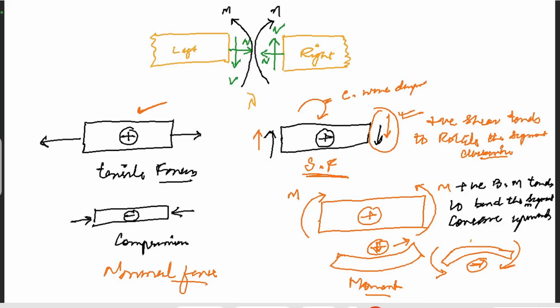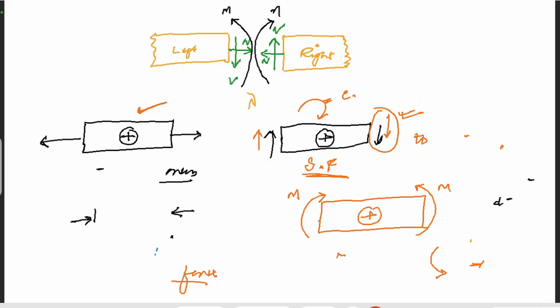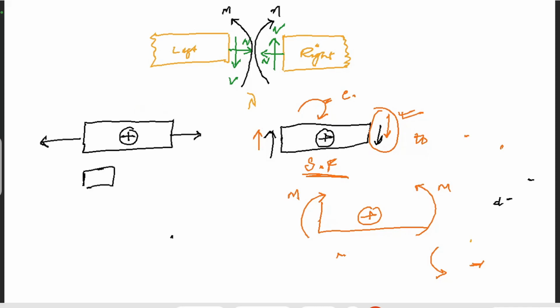You can add things in order to understand it more. Now when we were talking about the normal forces on this segment, when we make a cut, for example, this is a cut. Therefore the direction will be this, pointing outward, normal force when we make a cut, right? This is how it will be at the cut point, and it will be elongating it. So you can say this is a positive normal force.